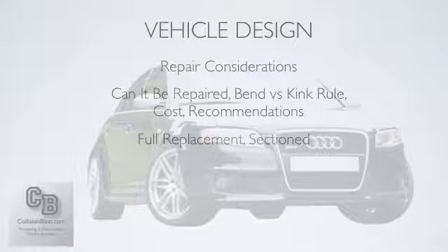But a lot of times you can get by with sectioning. For example, a quarter panel, rather than going all the way up to the factory seam, you can section it in a smaller area, like up by your back glass, without getting into the roof panel. So those are some different repair considerations. And again, until we get deeper into it, this is kind of an overview, some things to think about and consider.